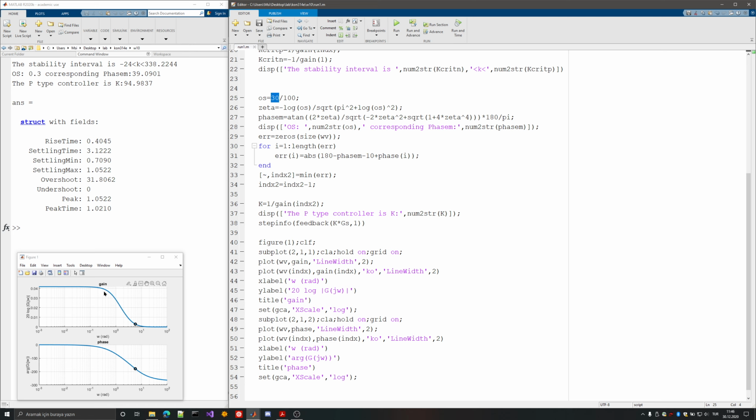But if you are lacking the mathematical model information, if you don't know exactly the model, if you have a black box, then your method will most probably give you a rough idea about the controller, not the exact controller. So if you have systems that can give you Bode plots, you can just go ahead and design for those systems using this design method. But if you have the model available, why are you bothering with the Bode method, frequency method, if you can just go ahead and use the time domain approaches?